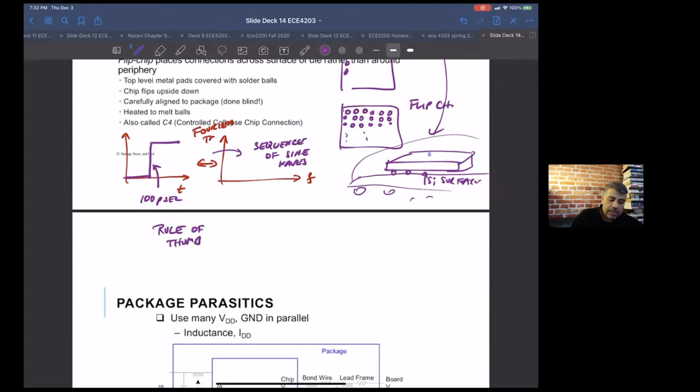So if you take your edge and decompose it into sine waves, it's an infinite series of sine waves, each one of which affects your rising edge less and less. So a rule of thumb for enough sine waves to reproduce a particular rise edge is that the top frequency is 0.35 over your rise or fall time, your edge time. Don't ask me where they got this number.